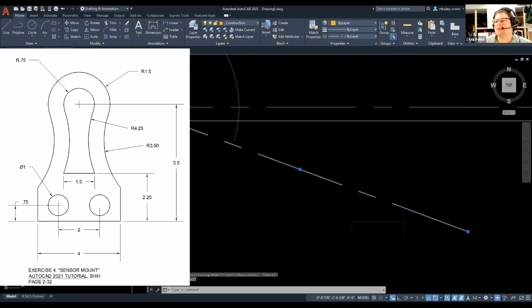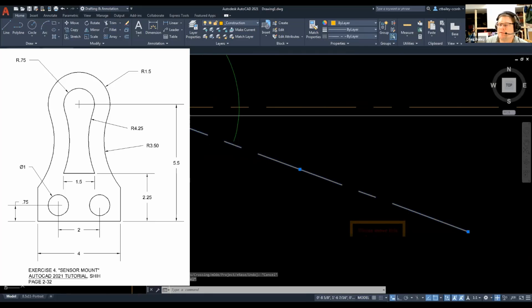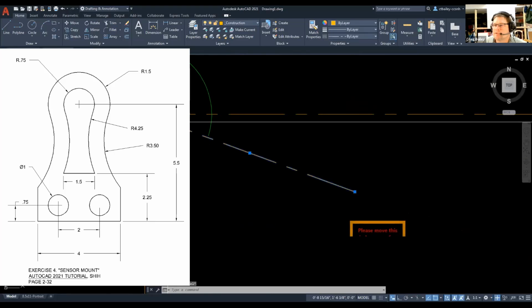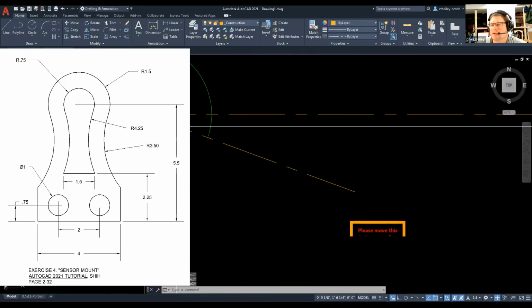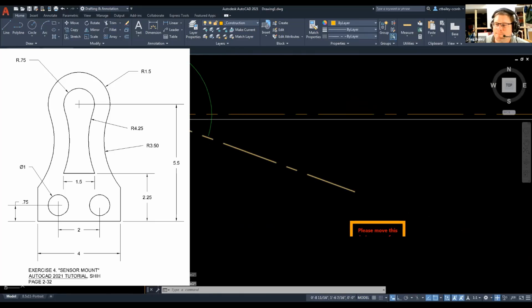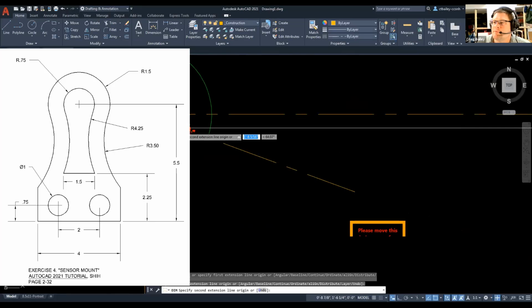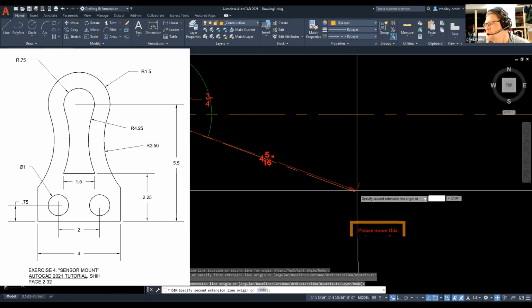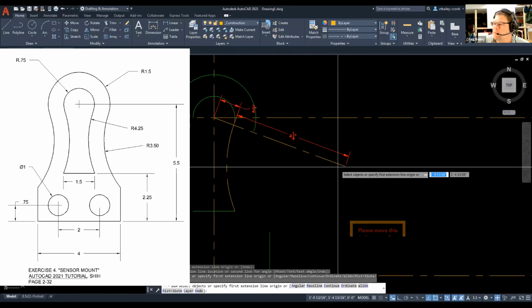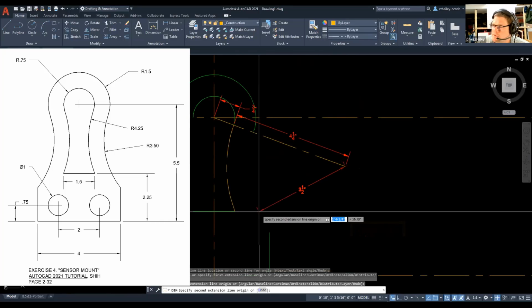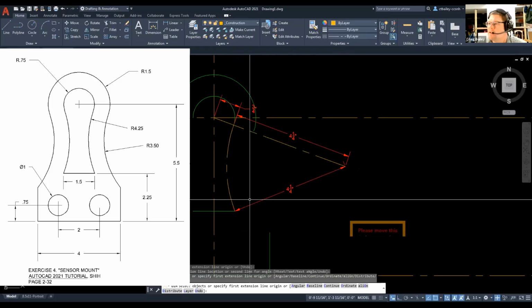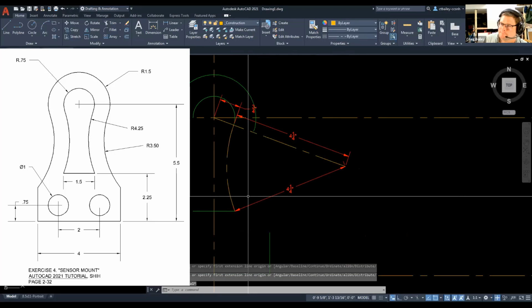See how, remember I said with a reverse curve, the radial lines from the inside to the outside have to be on one single line. And the trick to this one, and yeah, it was a trick, is recognizing that you had this dimension of 0.75 to here, and we knew that this distance had to be 4.25, and we knew that the distance from the center point of that magical circle to this point also had to be 4.25. We knew that because the circle goes through the point.